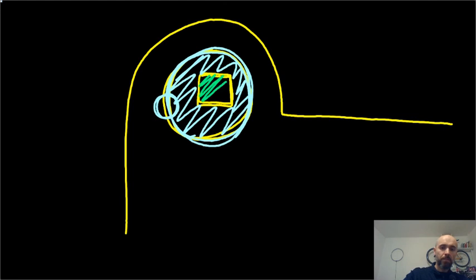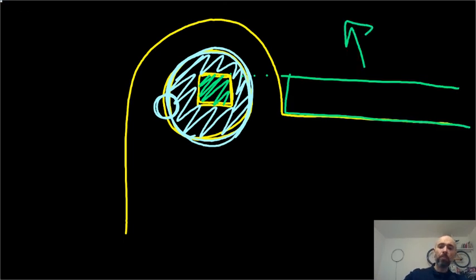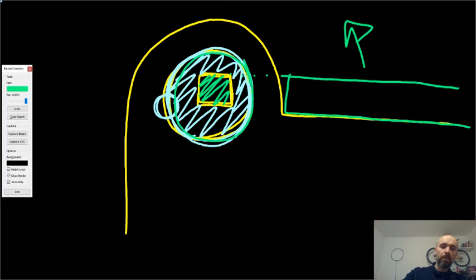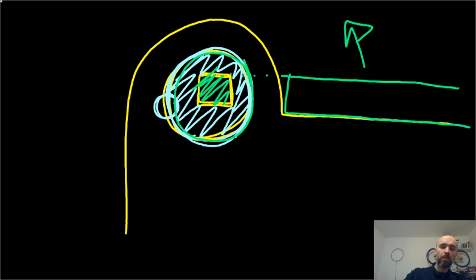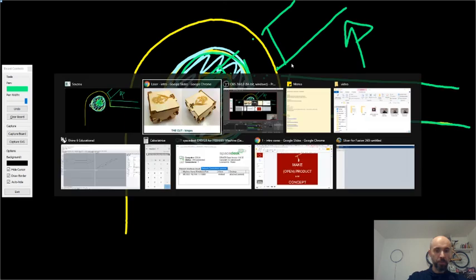here, the piece that actually goes on as the lid of my box, then when I rotate this, when I open it, this part is the one that rotates, okay? And it's glued together, so at a certain point I will have the square pointing this way and my lid opening here. This is the easier way to make robust hinges of two pieces perpendicular one to each other.